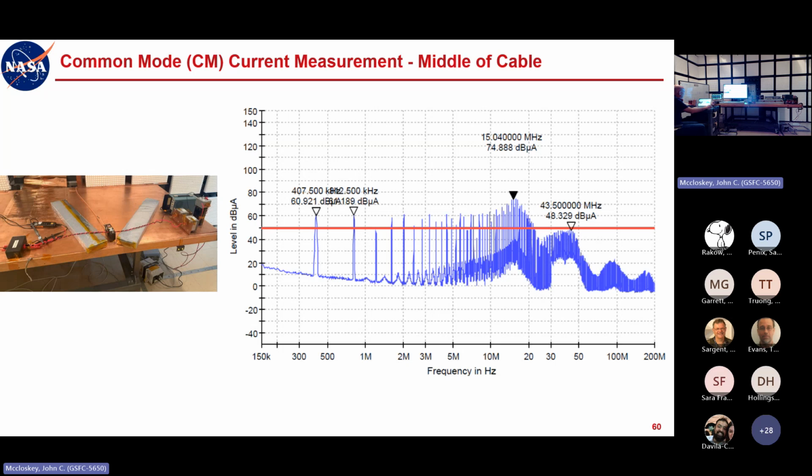But you're not terminating it in 300 ohms. You're terminating it, at least on the capacitor side, with what at higher frequencies is basically a dead short. Like I said, those will look like about an ohm at around 20 kilohertz. So in this whole frequency range of interest, mainly for common mode, you're dealing with these capacitors, effectively a dead short at these frequencies.